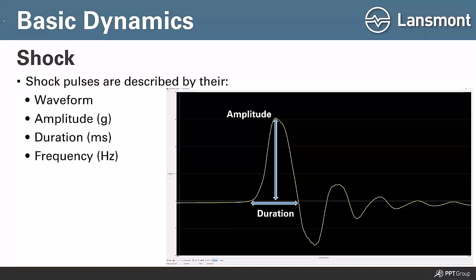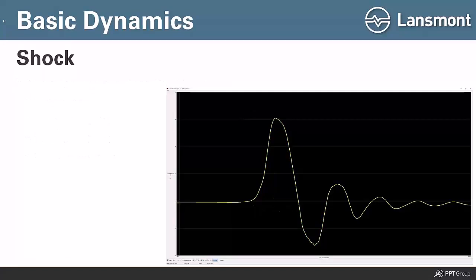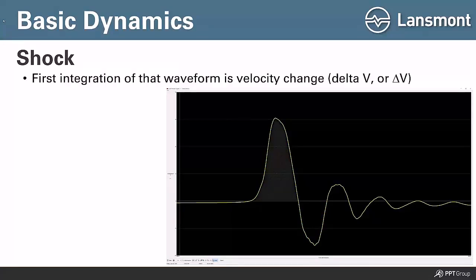That shock pulse that you're seeing there is a half sine shock pulse. What does that mean? That means really half of a sine wave, and we talk about vibration in terms of sine waves. It might be a little bit hard to see, but I drew a dashed line over that signal, and you can see that it has the characteristics of a full waveform overlaid on top of there. Knowing that, we can determine the natural frequency of that shock pulse.